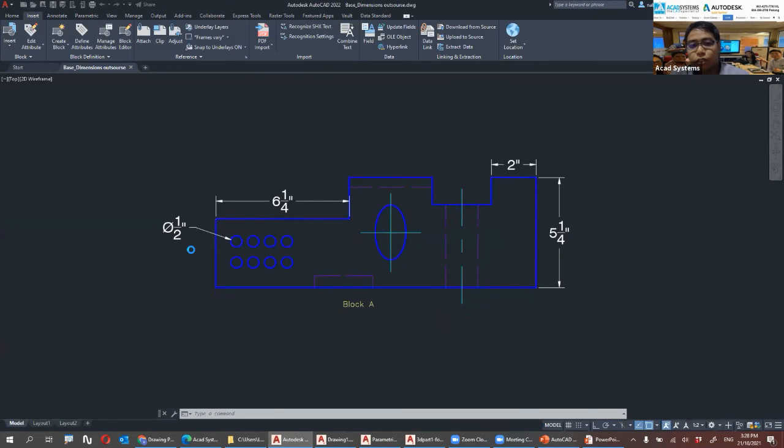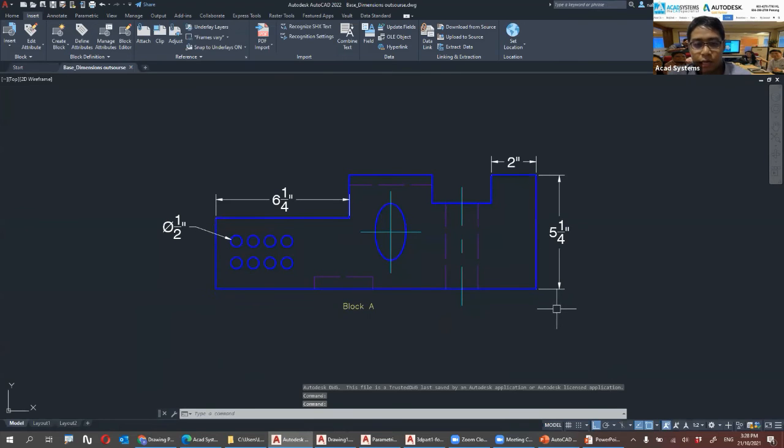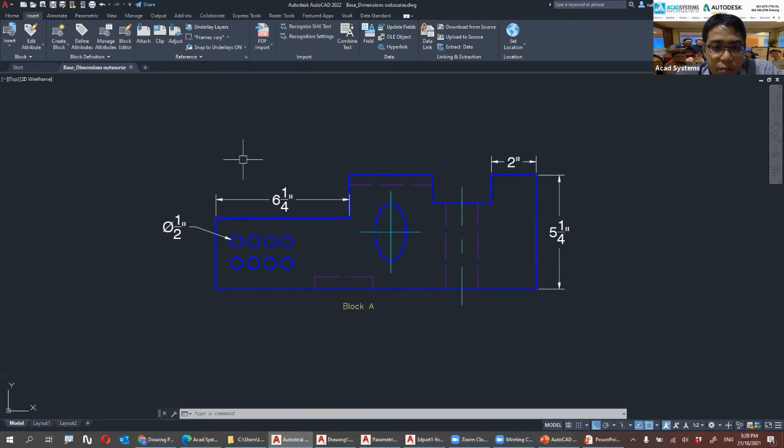All right, so let's say I have this drawing. This drawing is basically something I get from either my vendor or maybe from outsourcing. However, this particular drawing doesn't have the standard that I have been using. For example, from this unit itself, you can see it's now using architectural units, and maybe this unit is actually in inches. Some of these line drawings use different types of lines, different line weights, and different types of layers, which is not actually standardized based on my drawing.